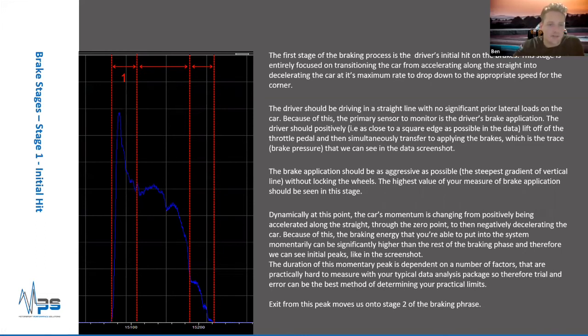which we can utilize. We can gain extra performance if we utilize all of it when the driver applies the brake. Again, using the 80-20 rule, the width of this is very hard to calculate dynamically. There's a huge amount of complex factors which are always changing. Track conditions change, brake conditions change, tyre conditions change, etc. So it's very hard to say you need to get up to 98.2 here, or otherwise you're not maximizing your braking performance. That's not really what we do, but we look to make sure we have this shape.